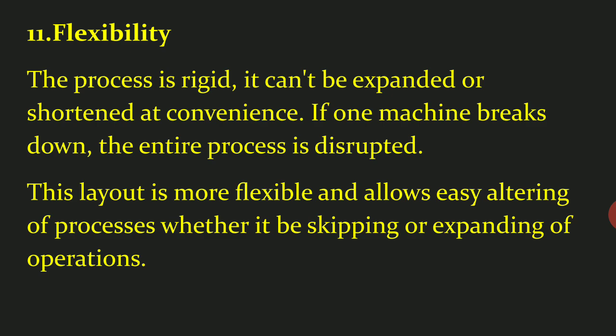And depending upon the manufacturing style, the manufacturer has to select that, okay, if my product is such, it does not require flexibility, I can go for product layout. But when my product needs flexibility, changes are often to come, setups have to be changed according to the customization, then at that time I have to select the process layout, right?